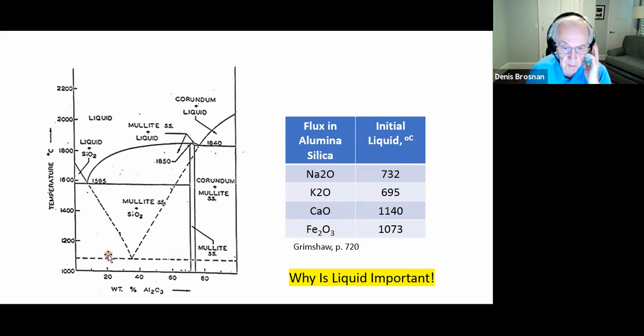This is about 1070, which is about the point at which alumina, silica, calcium oxide, alkalis, and iron oxide would give you a practical eutectic down here. So you're going to find out that most crude ceramics are fired up in this area around 1050 to 1070 to maybe a little higher degrees Celsius, taking advantage of that eutectic to form the glass to make the product functional.